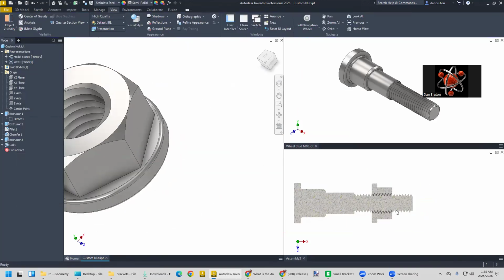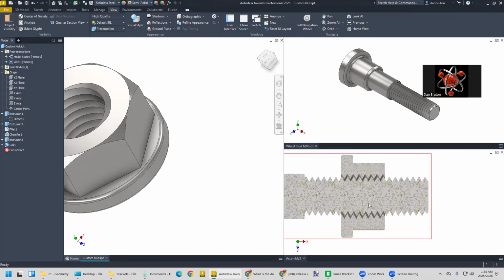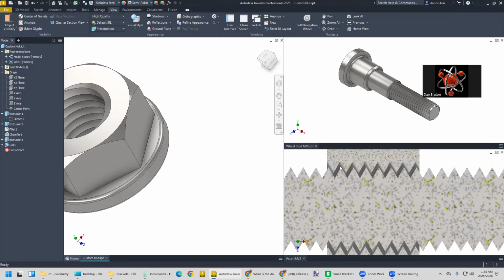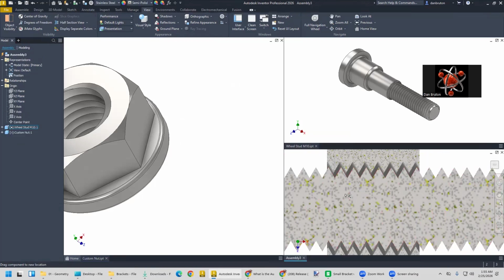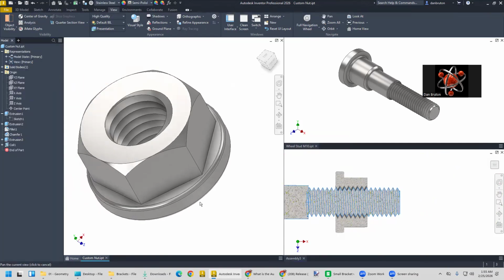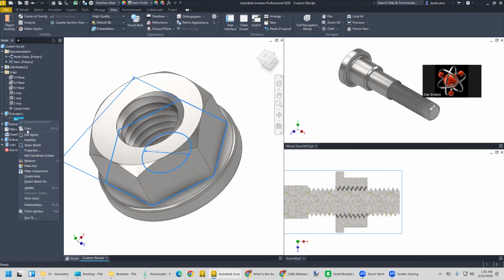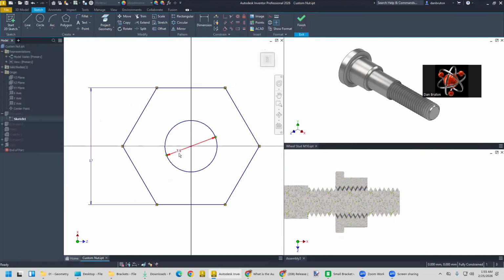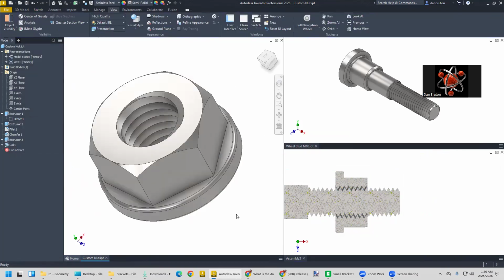And you can see that that looks a lot better. We still have some allowance in there so that it's not metal against metal in there. As long as that's about 0.4 millimeter, you're good. So all you have to do for this one is you can set this hole size right here to be 7.5, and we'll say that's good enough for what we're trying to do, which is reverse engineer a nut made